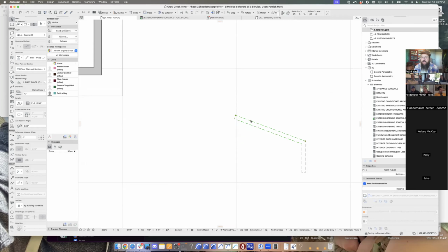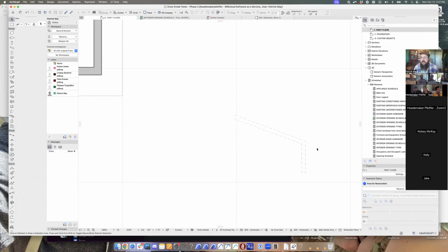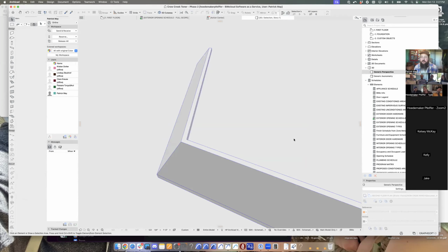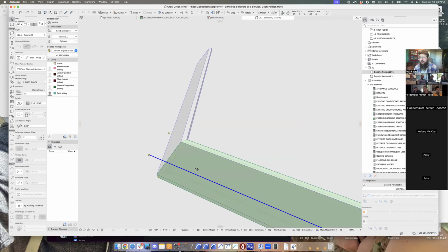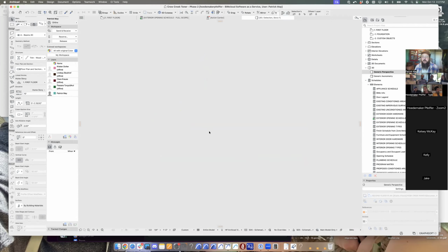And even more than that, if it's not even at a 90 degree angle, it's going to find that miter and it's only going to add one polygon to that face. It does get a little bit messy if you have sloping beams coming into horizontal beams. That's a whole other issue that we might do a breakout session on some other week.